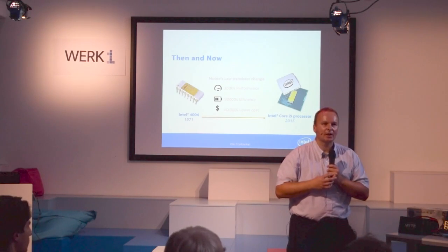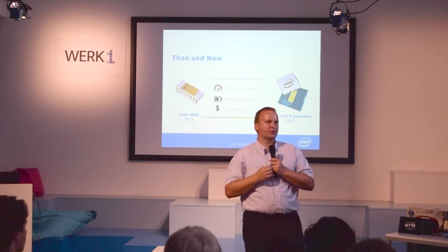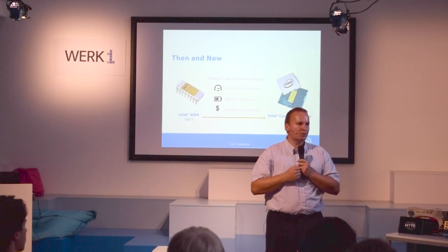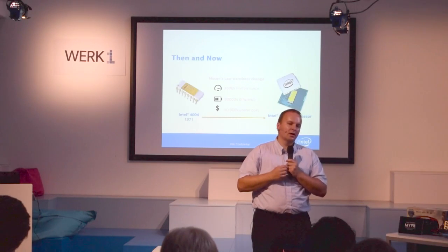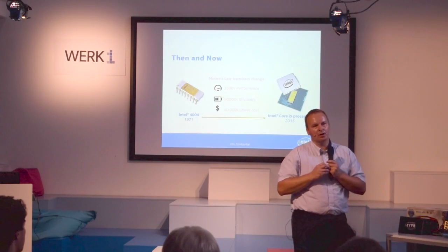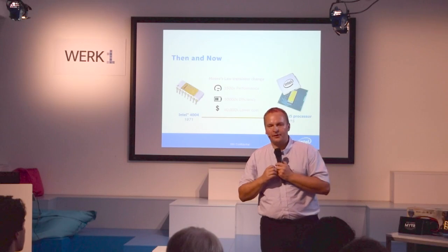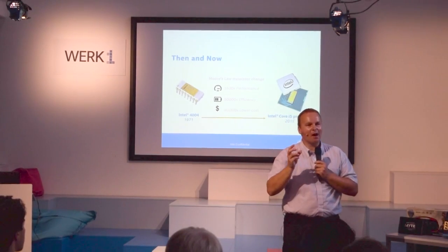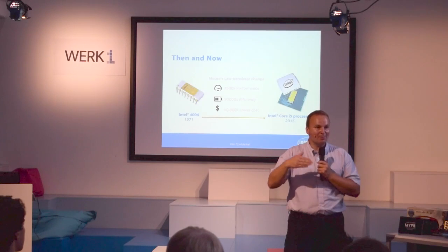What's the next step? Well, currently we're producing 14 nanometer processors. That's our current mass production node, 14 nanometer processors. We have 10 nanometer processors in preparation. Same wavelength still. That's the magic we're doing with the masks, with the optical proximity correction, with the multi-patterning.